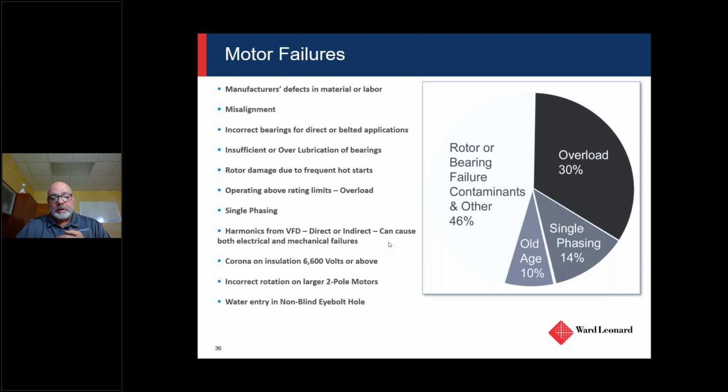So you will carry shaft currents into the bearings, and they'll fail mechanically just from harmonics and electrical current running through the shaft, right? So there's ways that we can get around that, though. We can help you with that. If you have a VFD and you're experiencing unplanned failures and don't have a lot of reliability in that, we can help you.